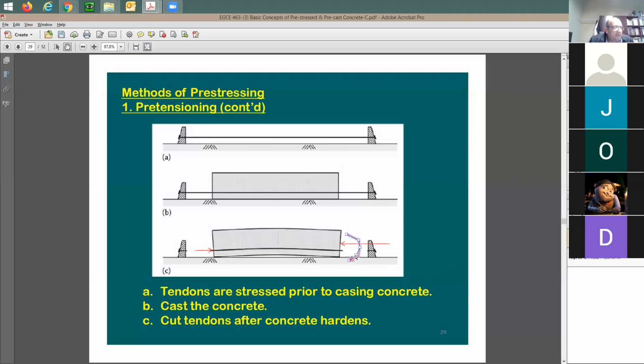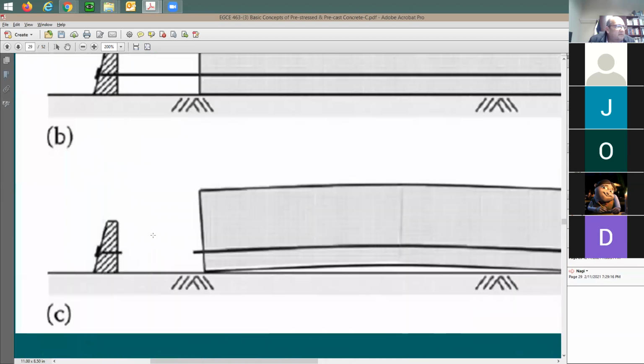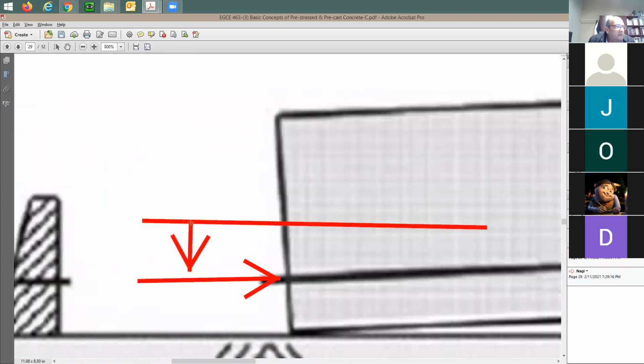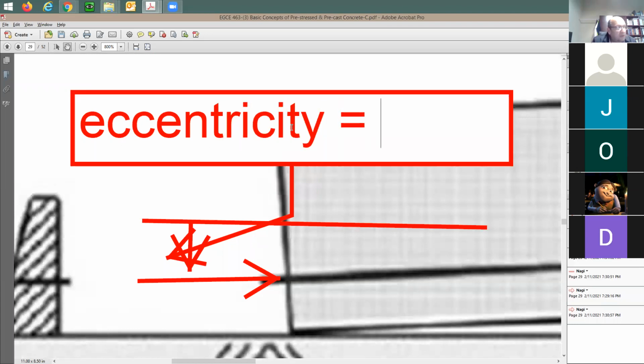So this is gonna be here, the beam moment that you have on the bottom. And this is again creating camber because you put the compression here at the bottom, right? When you put the compression on the bottom, this is equivalent to a moment and an axial load. And this axial load right now is gonna be right at the centroid, if you like to do your analysis. If you look at this distance, from the centroid to the point of the jacking, or the point of pre-stress, let's say here's the centroid, this distance from here to there, this is what you call E, the eccentricity. Usually we use the term E for it.